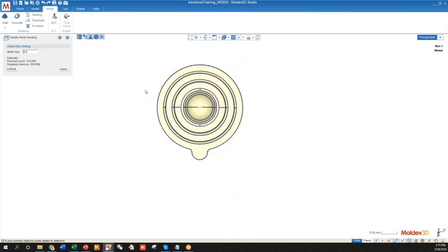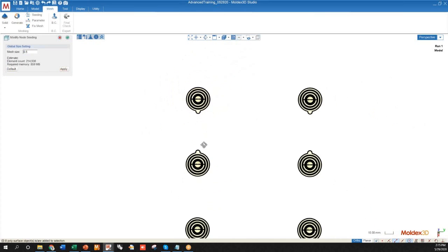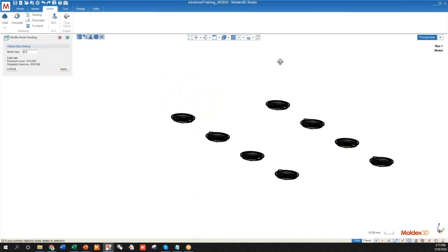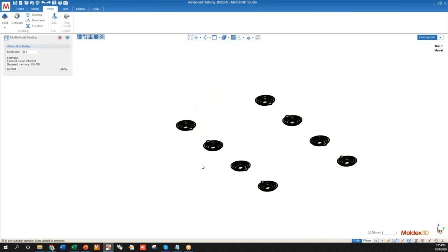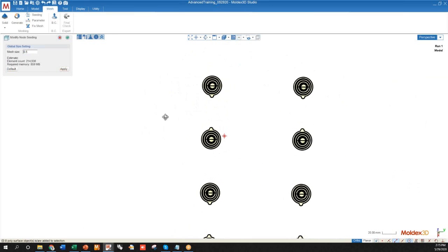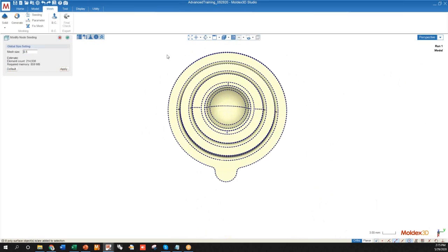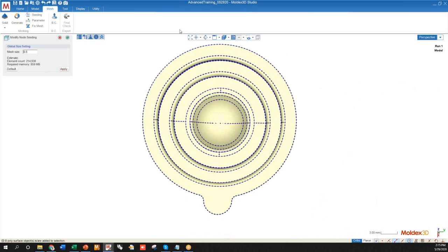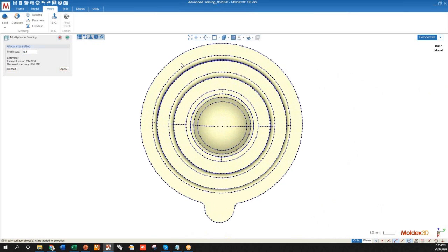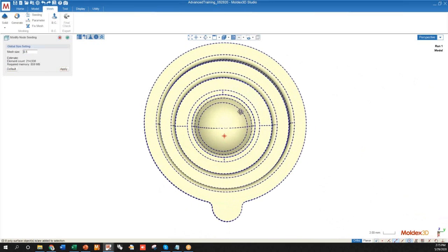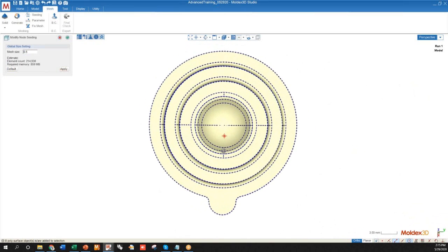All right, and you could make this a little bit more coarse if you wanted to. If you can preemptively figure out that you're going to have a huge mesh element size or a huge number of mesh elements, you can make a little bit of a sacrifice in this and make the node seating a little bit larger. Sometimes I do that preemptively just to make sure that my computation time is reasonable. Again, we're always trying to make an optimal trade-off between computation time and modeling accuracy.